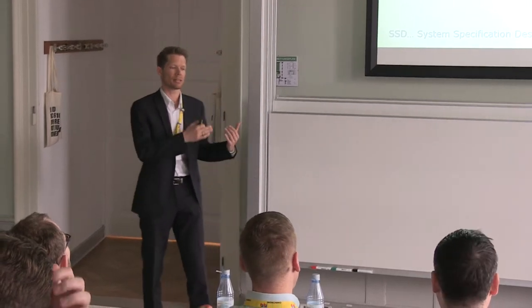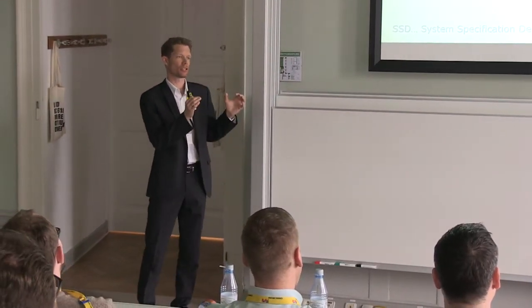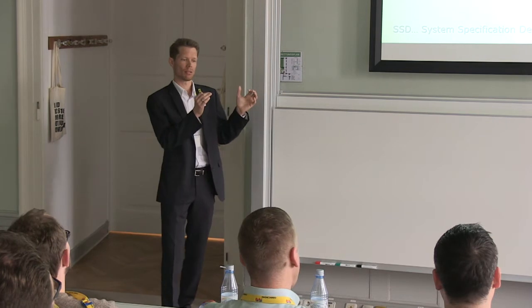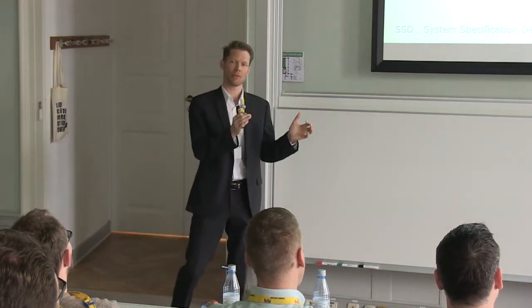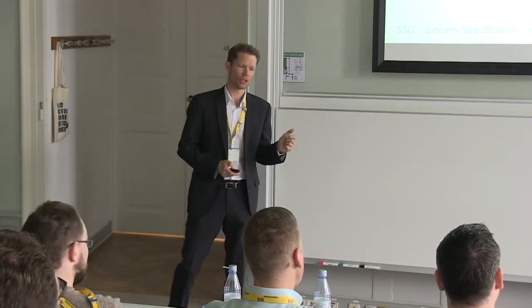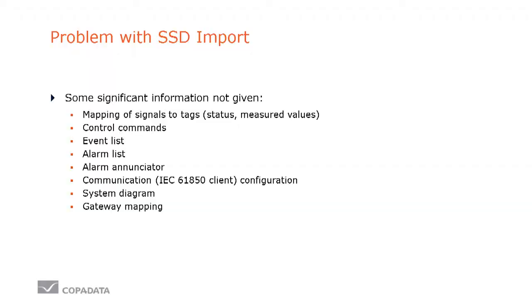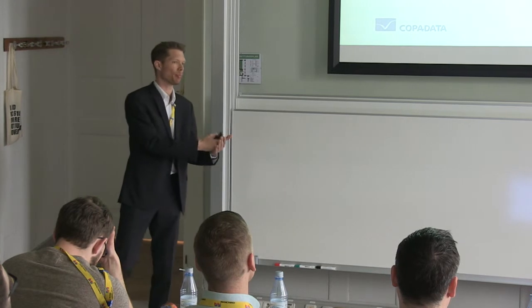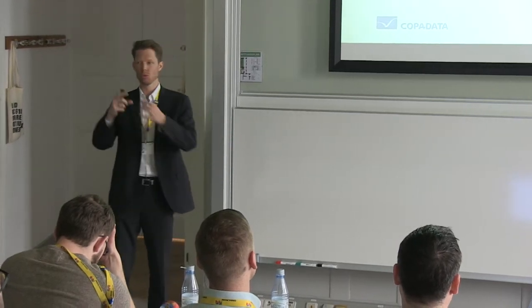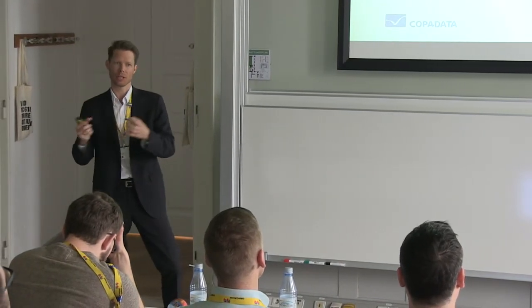As I said, the SSD file is the substation section. It does not provide enough information. Which information is missing is shown here. So we cannot provide an entire substation HMI just with the SSD file. We need more information because we want to map the signals to the text. So we want to map the attributes to the symbols that represent the circuit breaker, the disconnector.